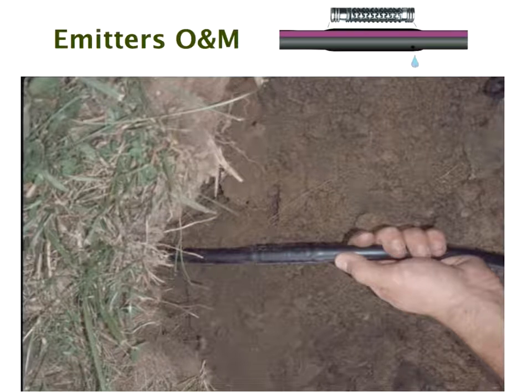The other risk, as we spoke about yesterday, is vacuum. Because of non-operative air vacuum relief valves, which is the usual reason, vacuum can suck sand back into the dripper and actually plug up the exit hole. Now, again, usually if you switch the system on and off repeatedly, with a short burst, it will dislodge it and begin to operate again.